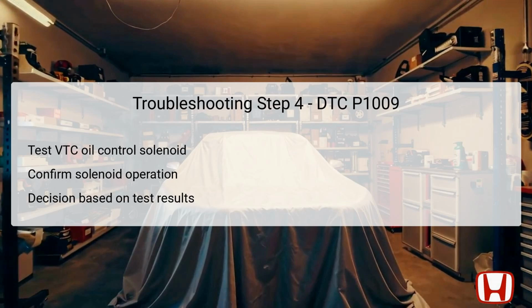After ensuring the VTC strainer is clean, the next step is to test the VTC oil control solenoid valve. This valve is integral in directing oil pressure to the VTC actuator, thus controlling the timing of the camshaft. If the solenoid operates correctly, we can confidently move on to inspecting the VTC actuator.